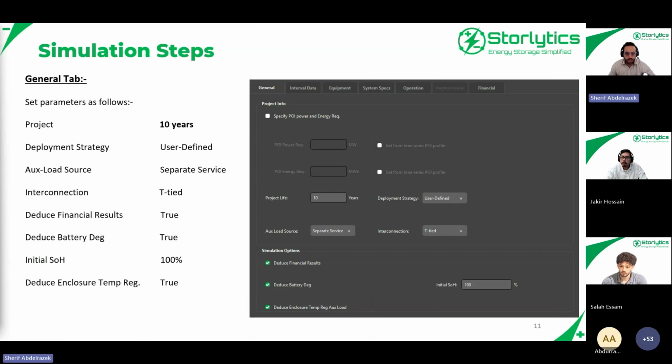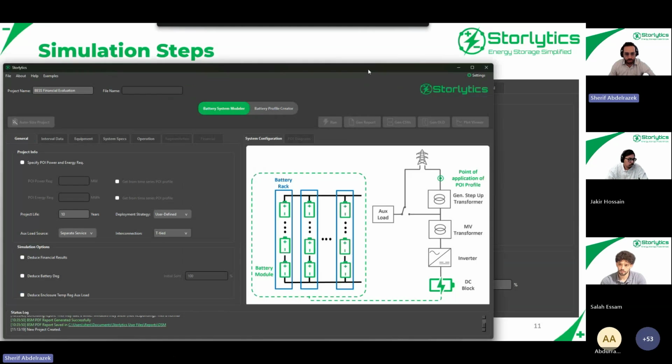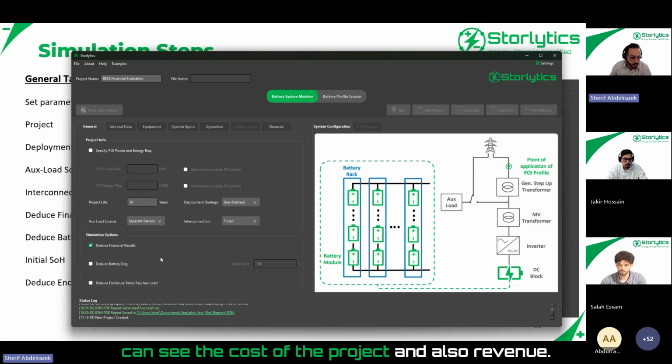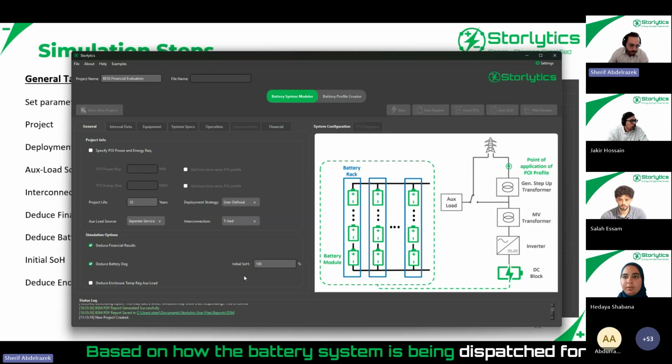Okay. And now we can move to the next step here, simulation options. So we'll turn on deduce financial results so that we can see the cost of the project and also revenue after we run the simulation. We'll also turn on the option to deduce battery degradation, which allows the simulation to calculate what the degradation will be each time step of the simulation based on how the battery system is being dispatched.